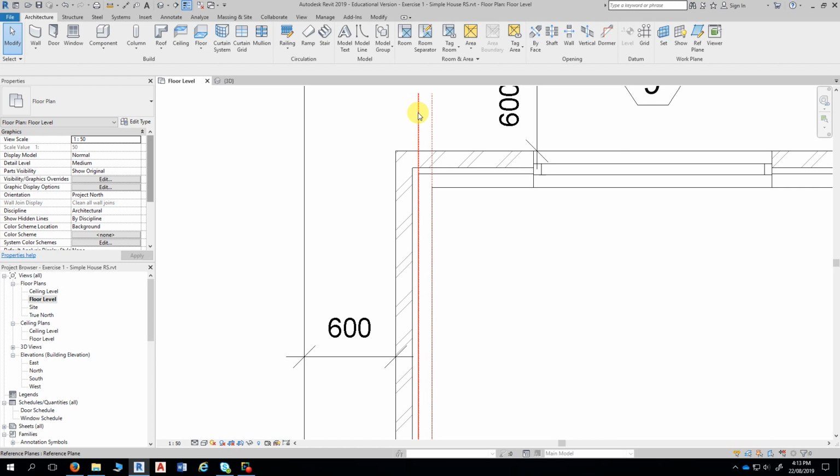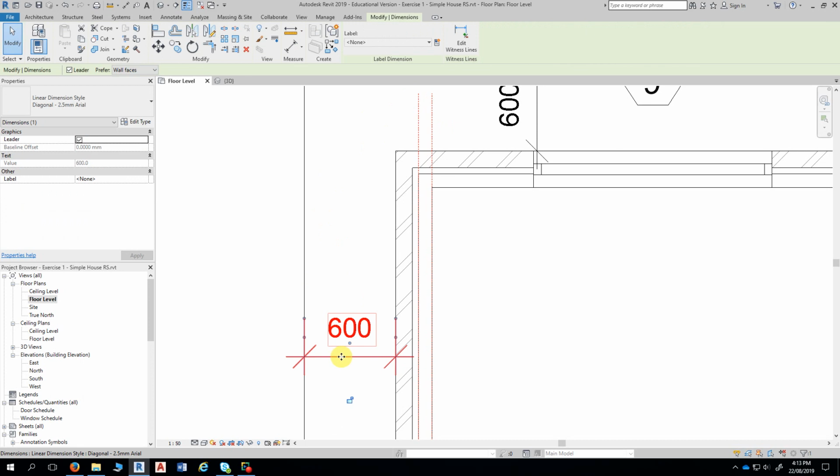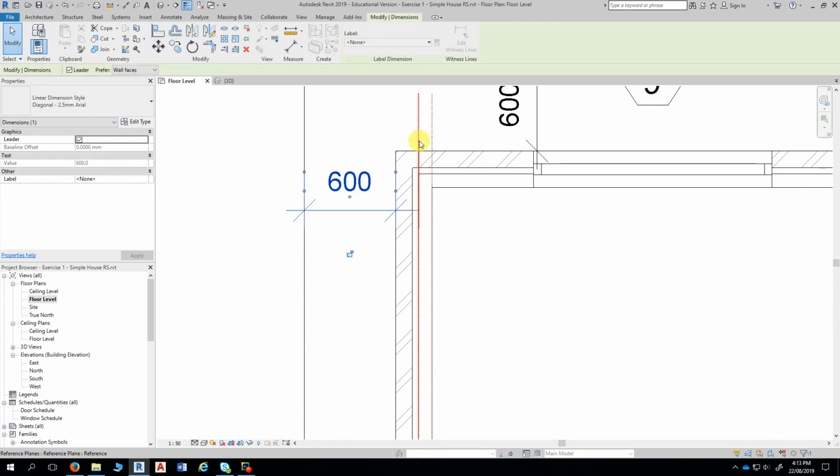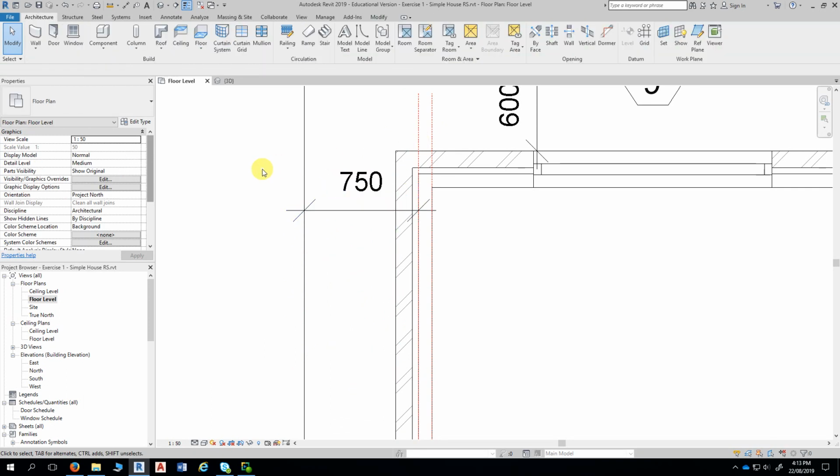So we're talking about conventional roofing here, but without going too deep at the moment, when we calculate the eave overhang, it's actually measured from the core, the external face of the core. So that's where the eave overhang is measured if we tick extend to core.